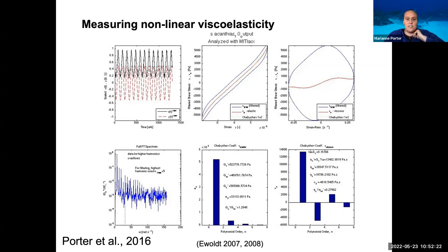And if we were just looking at E prime, that storage modulus, we would assume that this is nice and straight. So we make that assumption in our data analysis. Whereas if we look at the slope at the largest strain and the minimum strain, we're going to see something a little bit different. And so this was for our stiffness values or our elastic moduli variables.